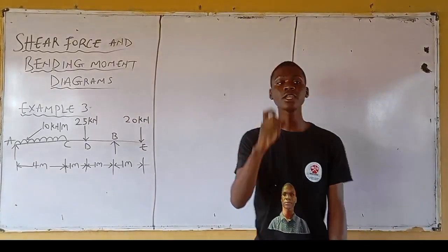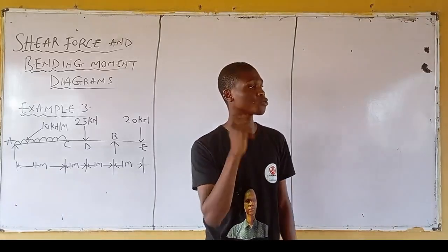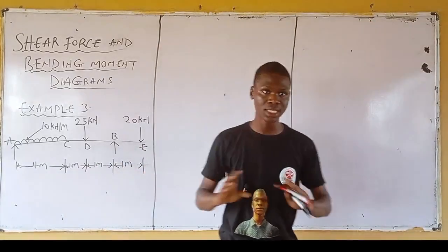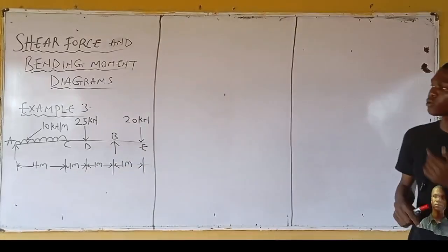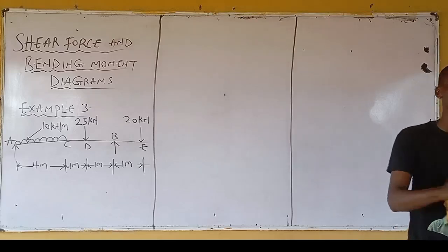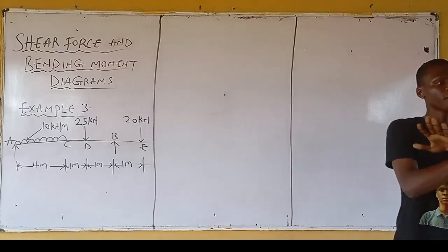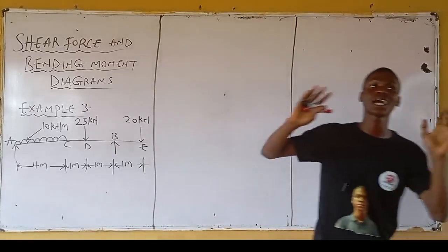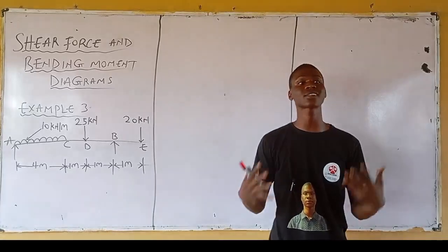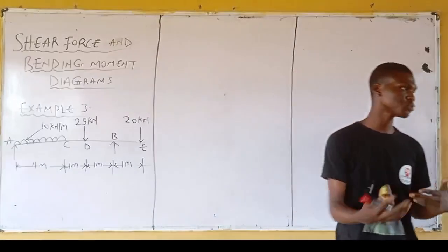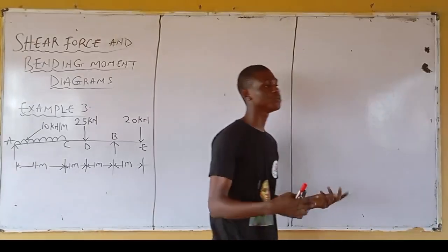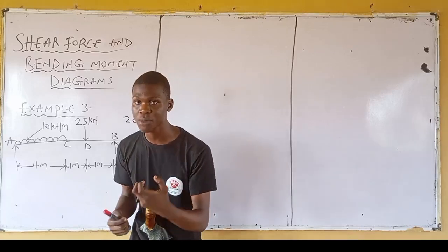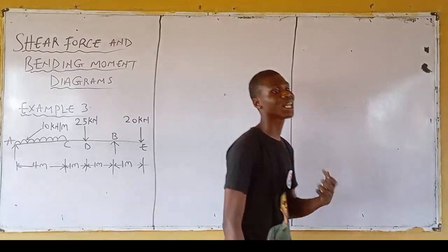Meaning that given a question, you are able to solve that question yourself from step 1 up to the last step; nothing is changing. Looking at this beam, I said for our level, given any type of beam in the exam, you'll be given only a statically determinate beam, right? What does statically determinate beam mean? It means equations of equilibrium are sufficient to analyze them.